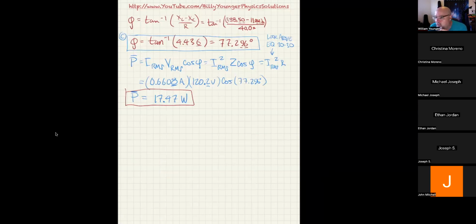And because of that, you can take the positive peak of, say, the first one and then compare it with one of the negative peaks of the other one. They'll actually line up enough that you can see the net effect is there's a 240 volt difference between the peak and the negative peak. That gives you 240, which is what we use in stoves, what we use in dryers as well, but not washing machines.